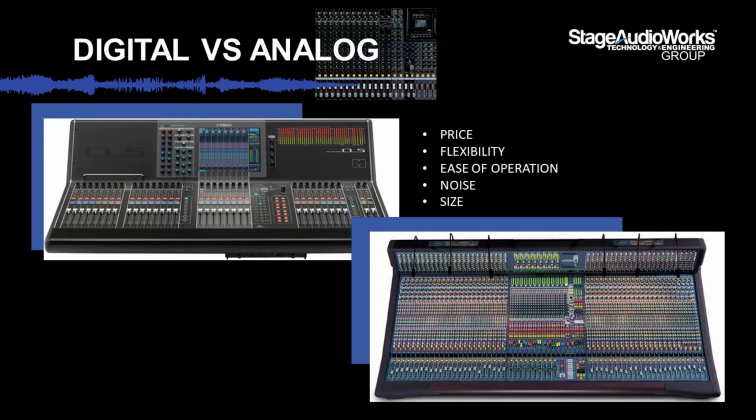So in an analog context, if you wanted to compress 10 channels, you either need 10 separate channels of compression so that you can have different compression settings for each channel, or you have to group a bunch of channels together and compress them all with the same settings. Whereas in a digital console, you have a compressor you can insert over every single channel. Same with effects, gates, and EQ. So the cost comparison is a bit of a loaded one, because gathering all of this outboard gear gets very expensive.